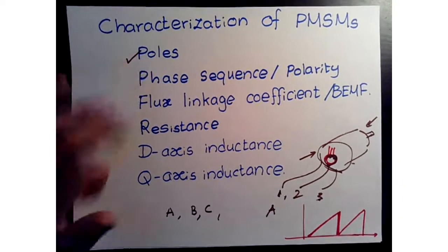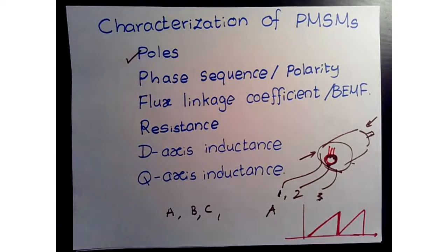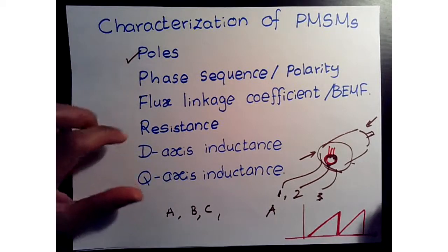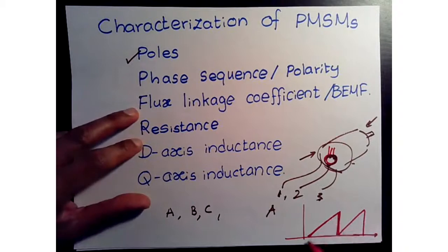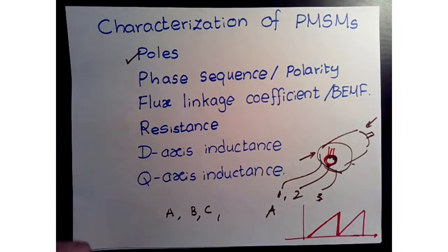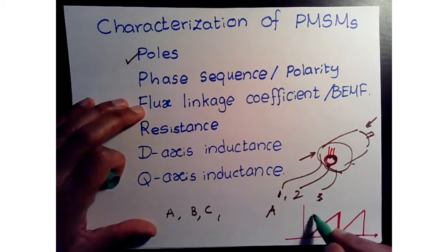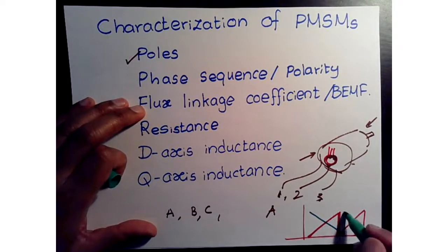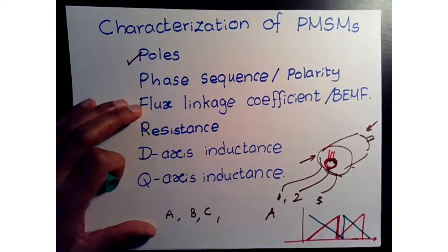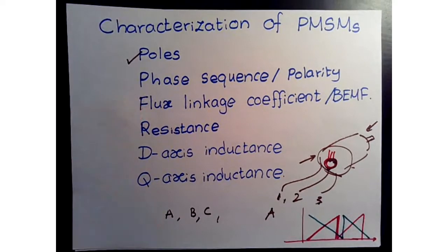Some sensors have sine, cosine, but we're not talking about that. Those sine, cosine signals can again be converted into this ramp signal, which is the position signal. Okay, and then when you rotate in the opposite direction, guess what? You're going to see the opposite slope. And these are not aligned, by the way. I'm just showing you the difference in the slope.